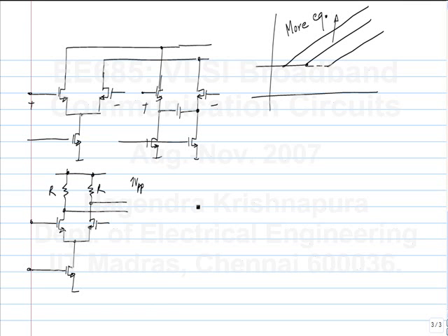So you can do two things. One is, let's say you find that one tap FIR equalization is sufficient. So you connect one tap with opposite polarity and supply the delayed input, okay. That's what we do for the FIR equalizer. So let's say this size is, if this is 1, this is 0.2, okay. So what is the steady state amplitude of the output of the equalizer?